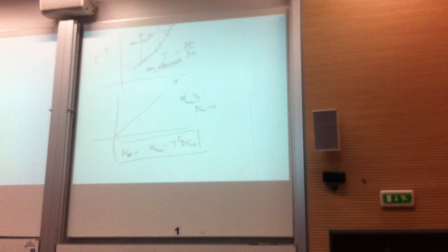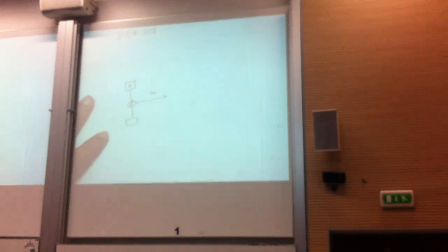All clear. Next comes the real stuff, and it is the steps that I have always been emphasizing you to learn. Put them into your minds, if not hearts. Number 1, draw a block diagram. Number 2, write down the energy balance. Number 3, write down the entropy balance. Number 4, see what is required and then do the manipulation. For example, when you are doing something, you write, this is a system A, this is a reservoir R, and you are actually getting some work output.